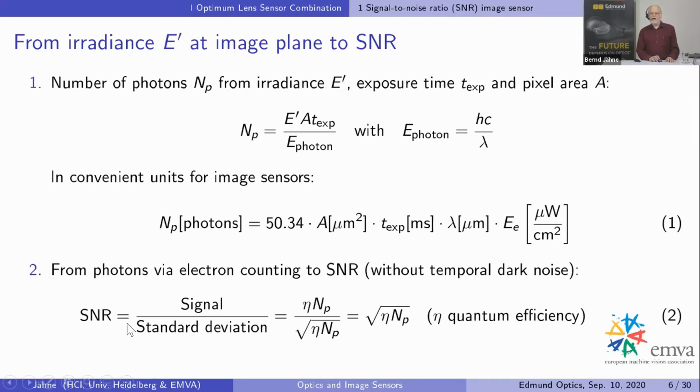And so we end up basically with the signal to noise ratio, which is a true measure for the quality. The question is not how bright the image is, but what is the relation between the signal I'm interested in and the noise, temporal noise, which is in the signal. And so you see, the more electrons we collect, the higher the signal is. And since this is just the energy received, you can easily see that answer 4 is correct in this case.